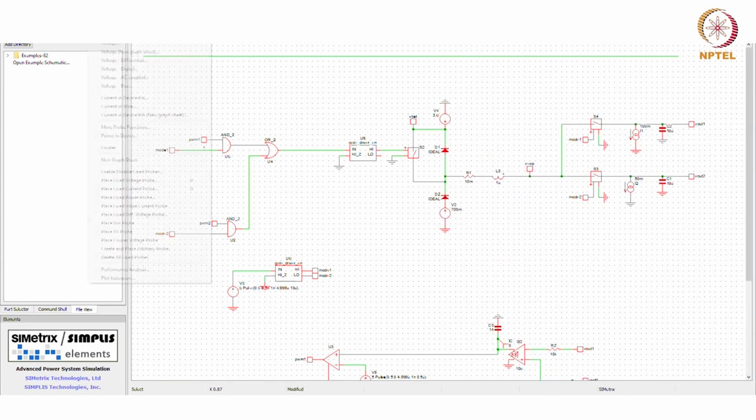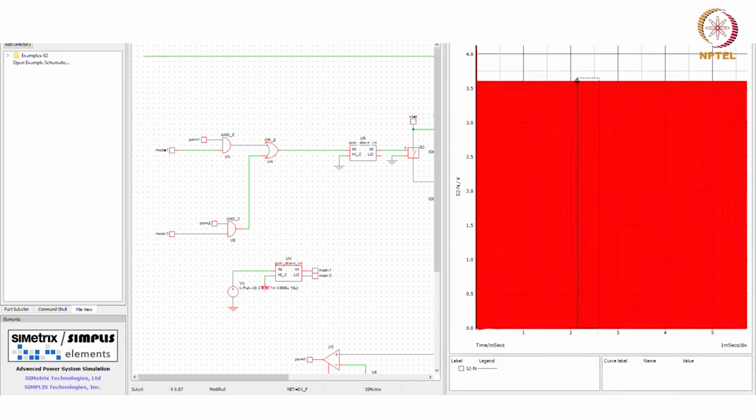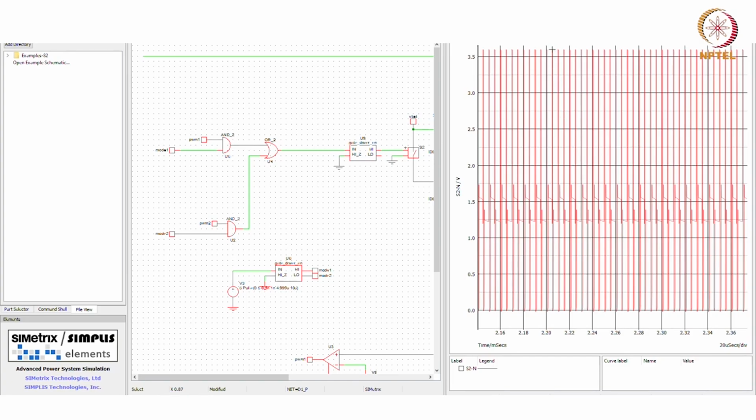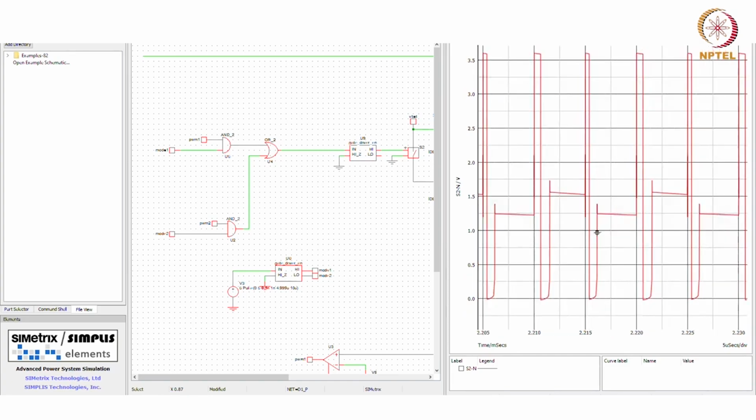And your switch duty cycle will also be different for this side. You can see the on time is different compared to this one. Okay. And you can see during this portion the inductor is still resting, so you can insert one more output here or increase the load current basically. So this will automatically increase, so it will reduce the idle time.